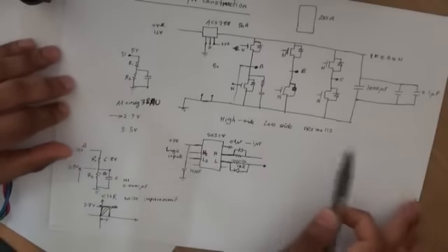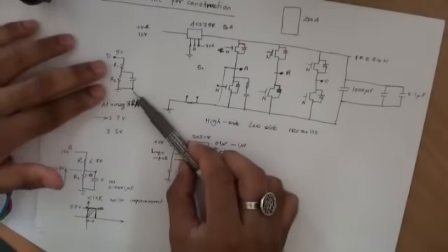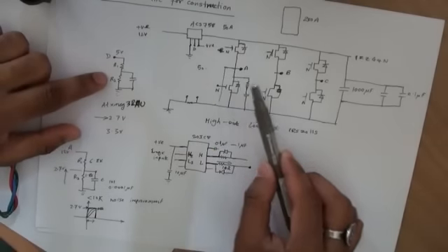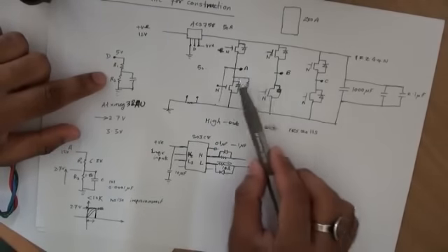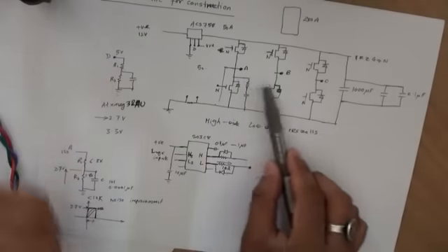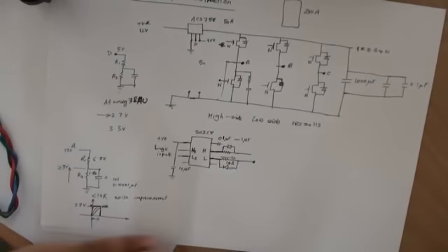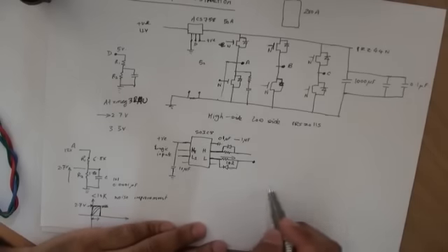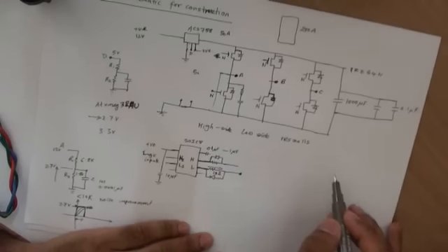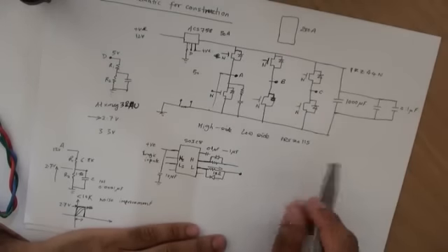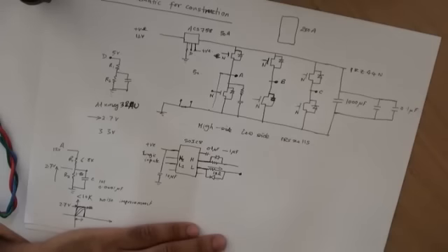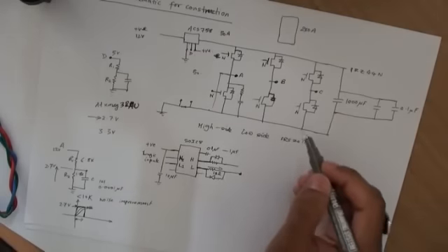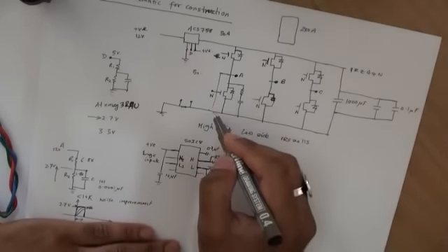So far you've got a current sensing analog input going to your microcontroller, and 3 other analog measurements, one for each of the phases. So you have the ABC 3-phase. The last one that you would like to have is the voltage reference. So what we are really trying to do is, with the phase readings, we are trying to find the zero crossing for each of the phases.